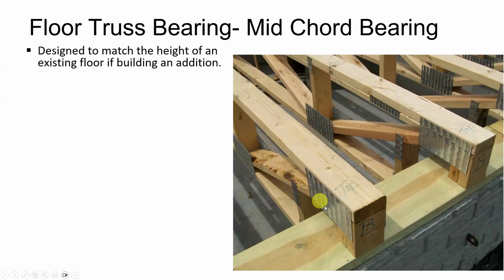So here in this case, you can see this is a 2x4 laid flat, and then these are 2x4s, and these are called gang nail plates. I'll show you more about how they make trusses, but just to give you a little peek. These gang nail plates have very, very sharp fingers, and you lay these things all out on a table. In some cases, they actually have lasers coming down on the ceiling that show you exactly where they lay these things out on the table. And then they put these plates on top, and then they just hit it once with a hammer to hold it in place. And then there's this huge roller that rolls over the trusses and presses them all in. And it makes those joints lock together.